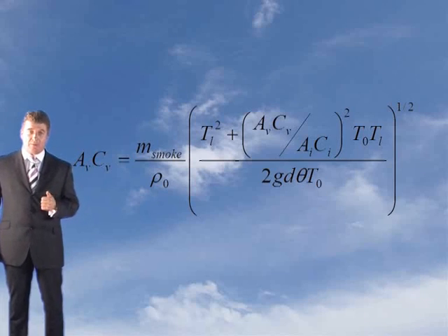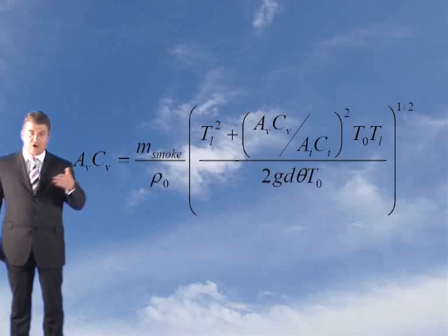We know how much smoke is being produced. Now we need to know how much area of ventilation is required in each reservoir to maintain the clear layer height of 3.6 metres. And this is the formula you need to apply, the AVCV formula, which we've used during the course. Now, if you put in all your known variables in there, you'd have got this.